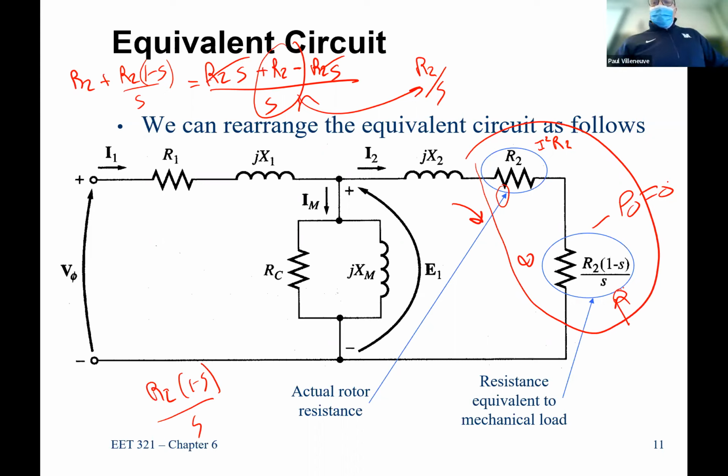Well, this is equal to 0, but now look at my current. Remember how I said in lab the other day, and for those who are not in lab, you'll see it tomorrow, I is going to be maximum at locked or blocked rotor conditions. All I have is just this little resistor R2 in there to limit the current. The current just flows through like mad because this is equal to 0. So my I squared R is going to be really high, not because R is high, but because I is at its highest.